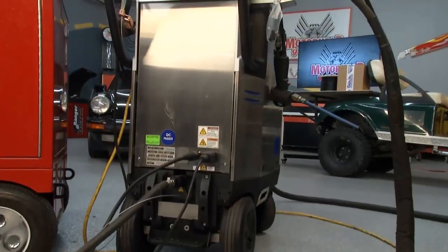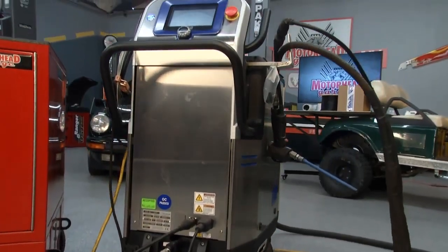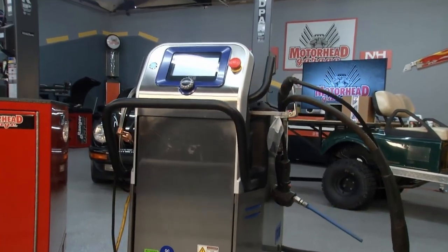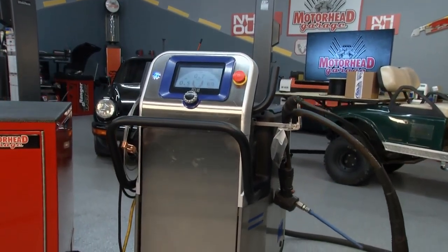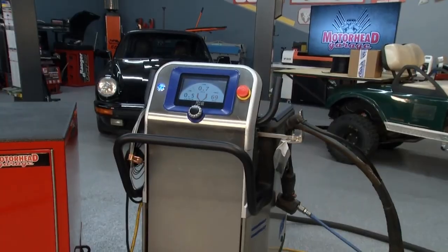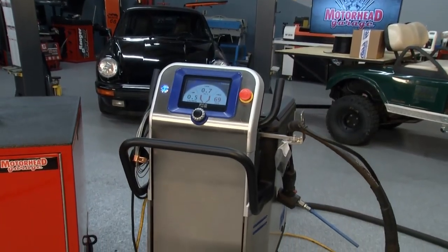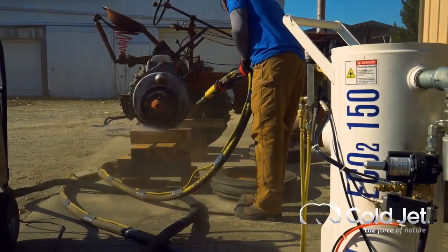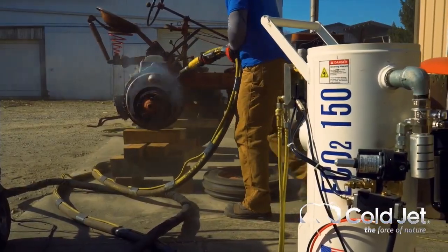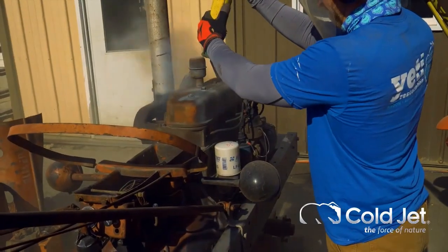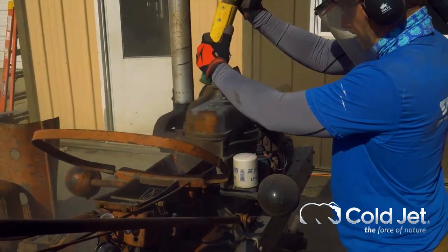And with all those things said, how easy is it to use a system like this? It's relatively easy. You've got your applicator, your nozzle, you hook it up, and there's about 5 major do's or don'ts when using this equipment. You want to be about 2 to 4 inches in most cases. Try to hit things at a 90-degree angle, but essentially it's kind of like a dry pressure washer when it comes to the operation.